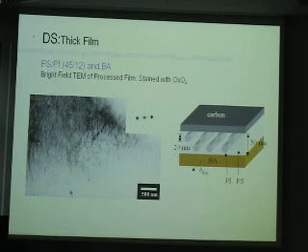But in the simple case, if you decrease the film thickness below 20 nanometers, which is the cylinder size, the cylinders no longer tend to stay in plane. The cylinder structure breaks up and tends to stand up on the substrate.